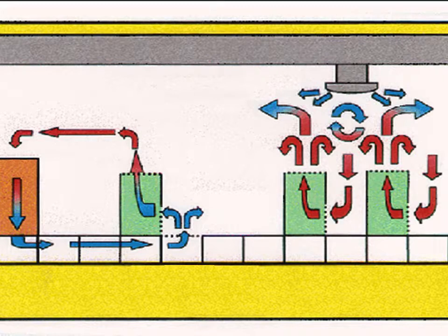If you recall, in a previous module, we looked at the difference between overhead ventilation, which is what you see on the right-hand side, where air is supplied from an HVAC unit, versus underfloor air, which is on the left-hand side, and how we can use the natural buoyancy of air to reduce the amount of energy.